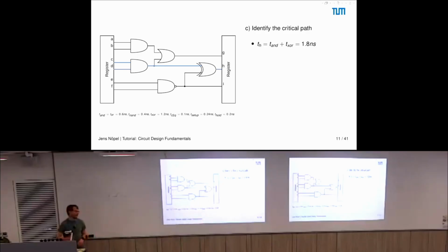So the second register expects that during that time window the signal does not change, because this is compensating for the fact that if it would change and we have some small variance in the clock, then we would sample just the wrong value. So it needs to be stable for a certain amount of time, and that is dependent on how the register physically behaves. So I guess I just continue.